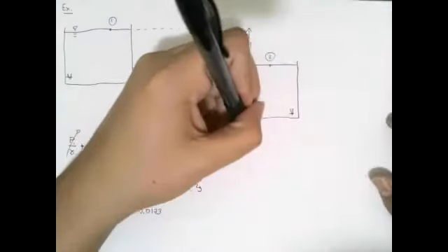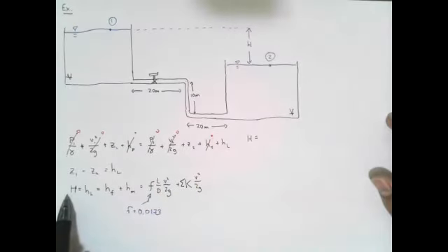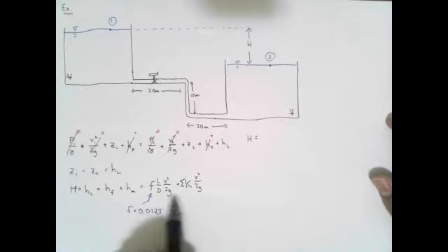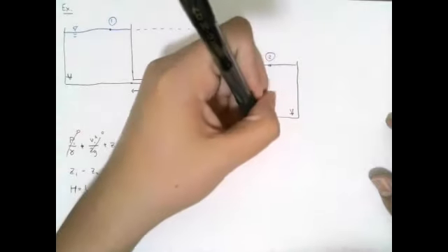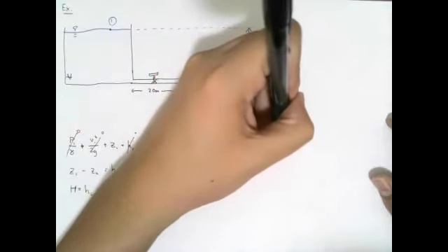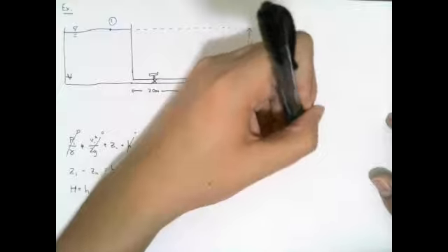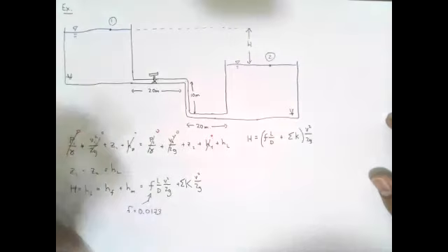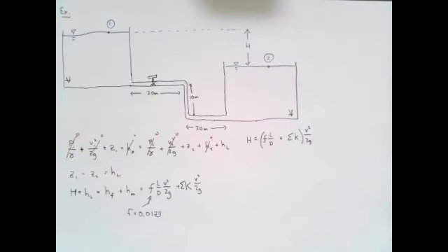So we look at the equation. Our H, our height difference, is equal to, I'm going to factor out my kinetic energy term, friction factor times length over diameter plus the sum of all of our minor loss coefficients, and all that multiplied by the kinetic energy head. Do we have the friction factor? Yes, let's say we calculated it. Do we have the length? Yes, we have the length of the pipe over which the friction is occurring, because Lauren asked the client to give us that length.